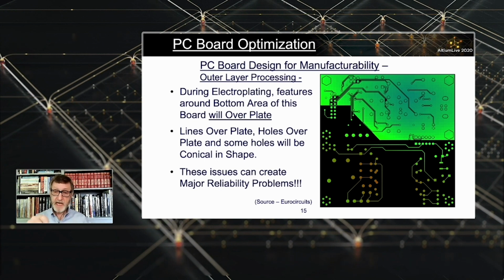What I should do is add copper pour all over the bottom area of this board, the bottom half of it, and attach it to something, to ground, to power, to something, so that the copper is balanced, so the copper will plate evenly in and on the board. And you need for it to be balanced on both the top and bottom of the board, not just all over each surface. Copper needs to be balanced all over the outer surfaces, and not only the outer surfaces.